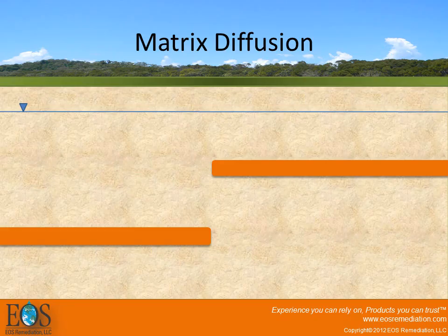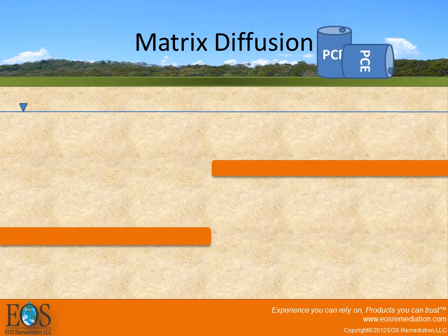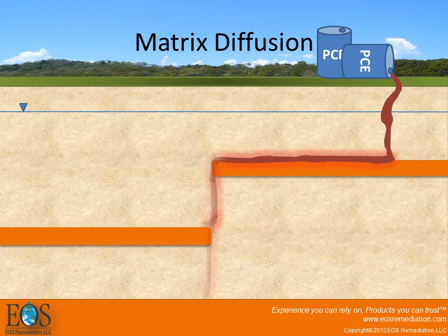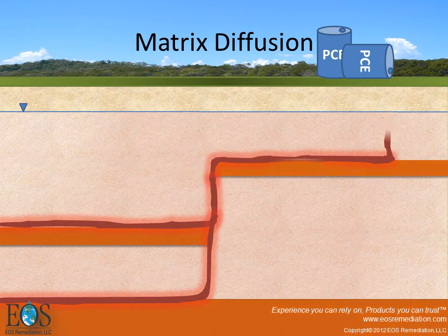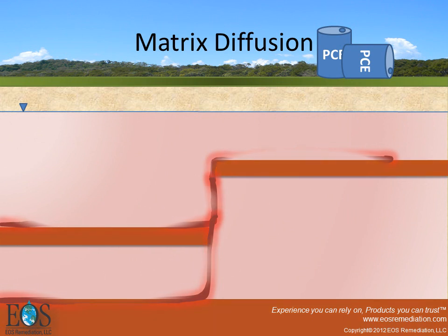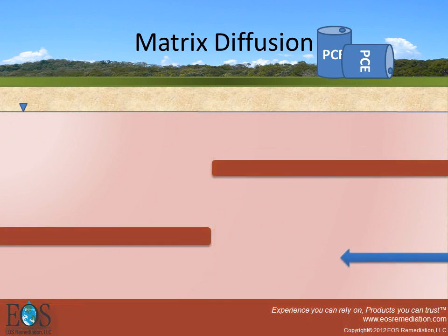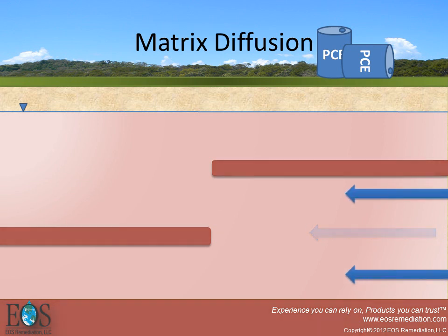What does this mean? How did these two things come together to form this issue? In this cartoon, you have your initial spill of PCE, and you have a DNAPL coming into the subsurface. As you can see, it rides down along the low K or clay lenses, and over time, it soaks in. So remember that something like PCE has an octanol water partitioning coefficient of 3.4. So it's very hydrophobic and it sticks strongly to the aquifer materials.